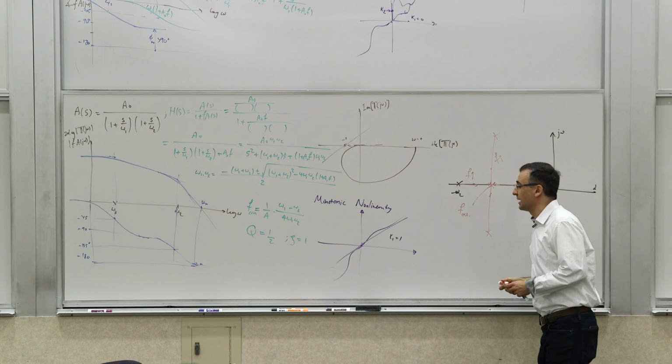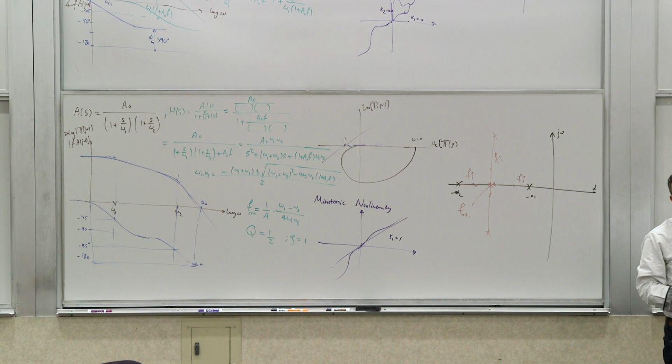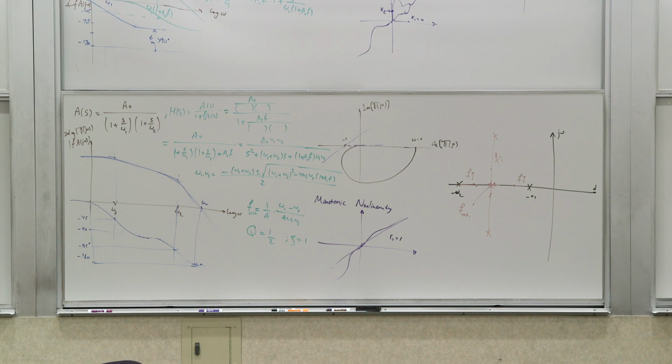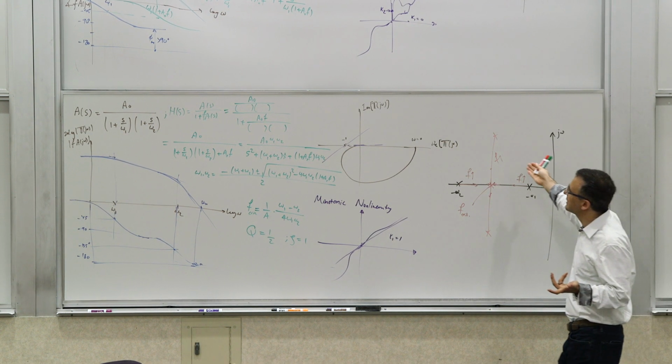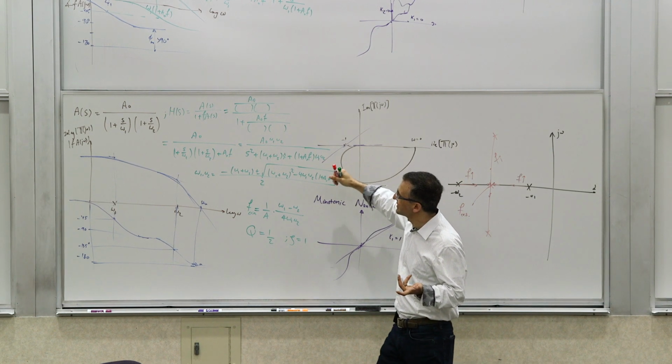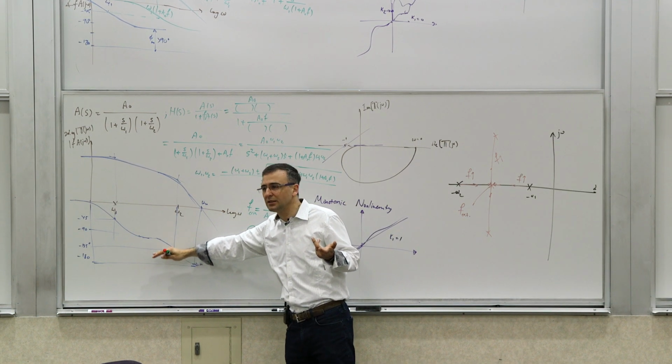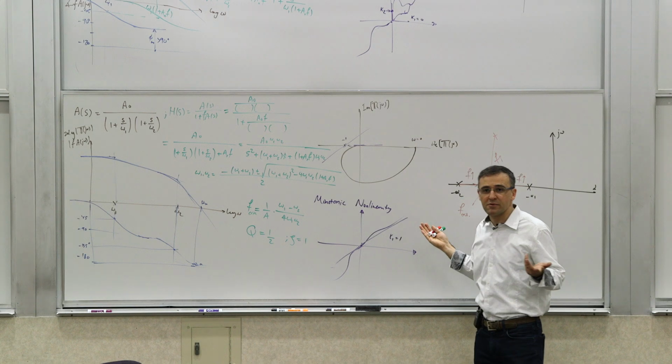This is still f increasing, right? But according to this picture, the poles never go to the right half plane, which is another way of saying that the system is BIBO stable. The linear system is BIBO stable, which is consistent with what we saw from Nyquist, which is consistent with what we saw from here and there. All of them should say the same thing.